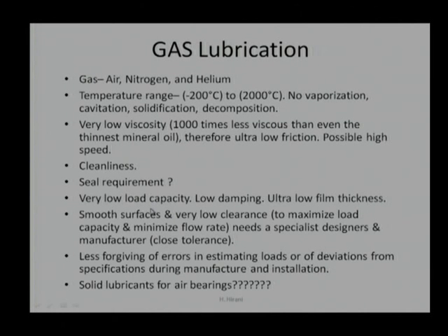We say this kind of lubrication is effective when the load requirement is not very high. The applied load is very low. We do not require any damping, or there is no vibration related problem. And even an ultra thin film thickness is sufficient to separate two surfaces. That means we require very good surface roughness of the tribo surfaces. Now, this is imposing a major design problem. The surfaces need to be very smooth, and by the way, if they come in contact, there will be very high adhesion.